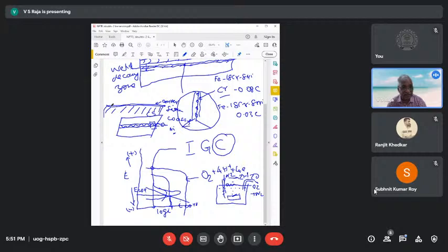So this is a coating primarily given in order to improve the adhesion performance of a paint coating. Suppose I give a phosphate coating and then apply a paint coating. Here, the paint coating adheres very nicely to this. Adherence is an important property for any paint coating. If it's not adhering, that's not going to be good at all. So the primary function of this is to give good adhesion.